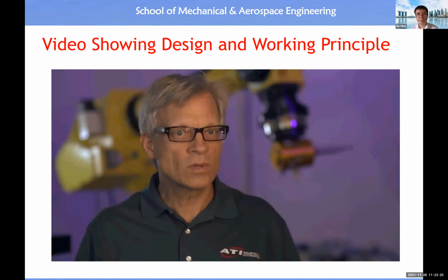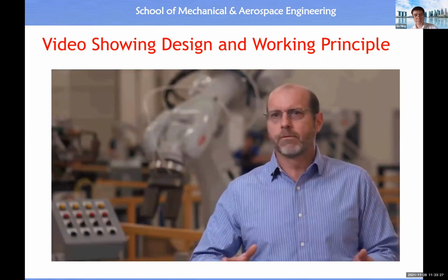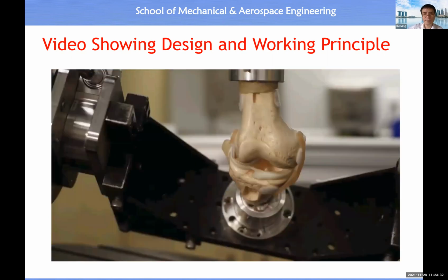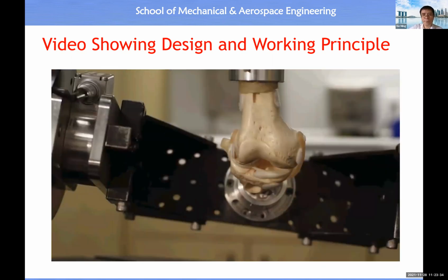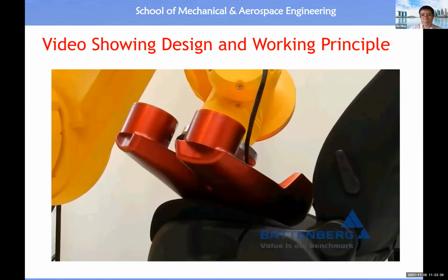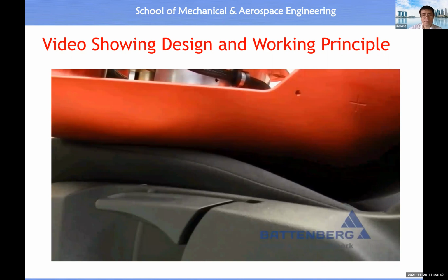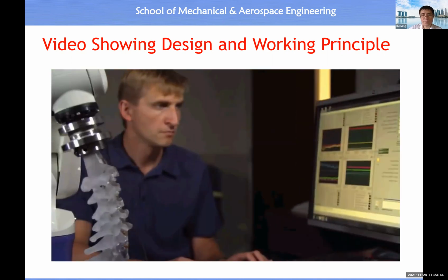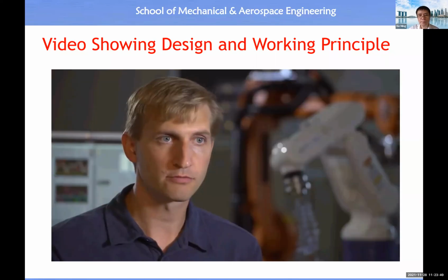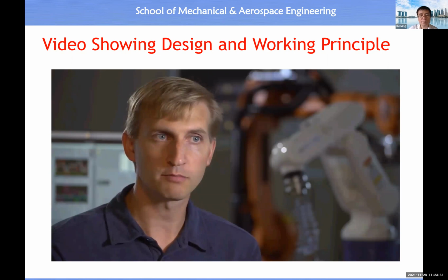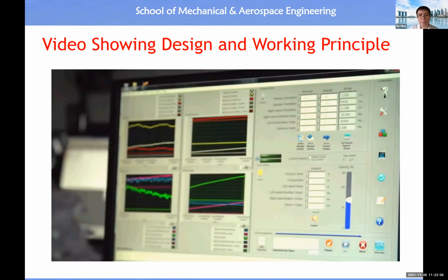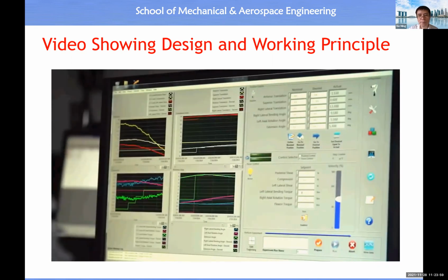The most important thing force torque sensing gives us is the ability to open up the robot to other applications where we normally wouldn't have that ability. Some of the more common applications for force torque sensors are product testing, life cycle testing, control of robots for surgery. The robotic technology with the full 6 degree of freedom of control gives you a lot of freedom that you never had before, because you need to be able to measure 3 forces, 3 torques to get the full loading state of any joint. And that's true for any joint. Once you establish that, you establish the full loading state of any specimen of any joint you want to do.